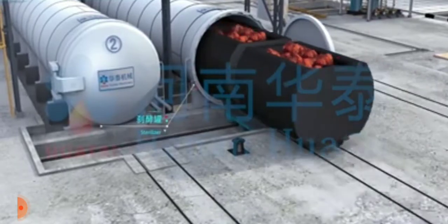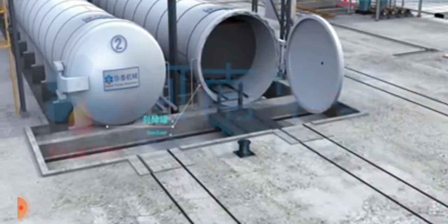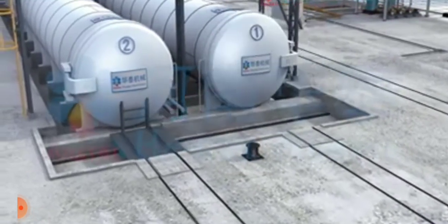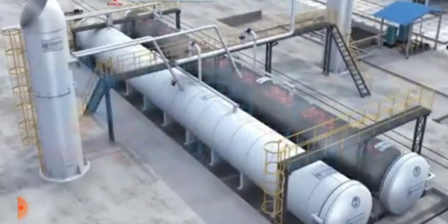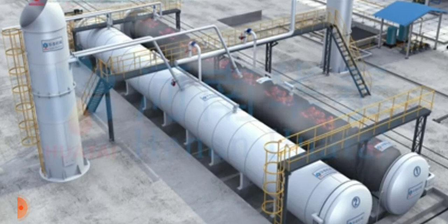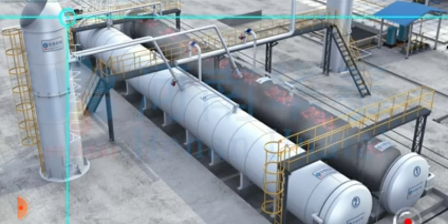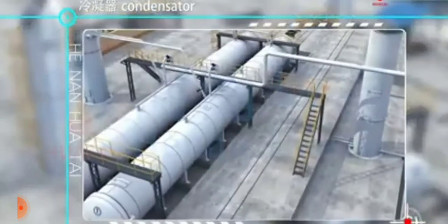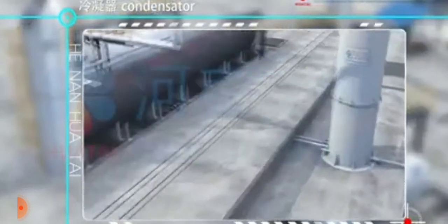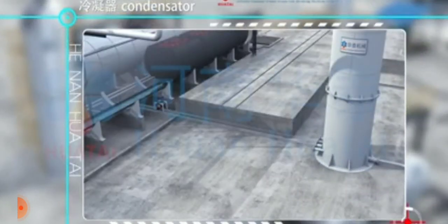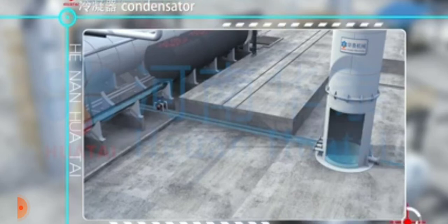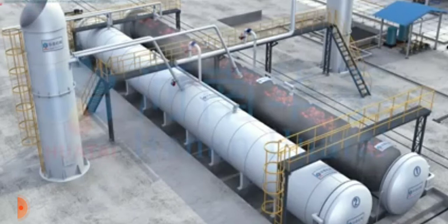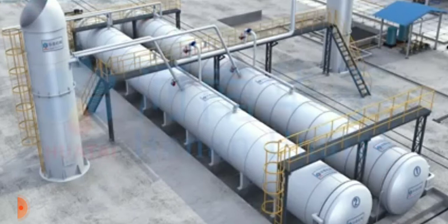For the horizontal sterilizer, after the sterilizer cage enters the sterilizer entirely, close the gate. Start filling with steam. Sterilize palm fruits under certain temperature and pressure. Condensate generated during sterilization is discharged to the condenser from bottom pipelines and then to the sludge oil pit. After reaching the preset sterilization time, empty the steam.